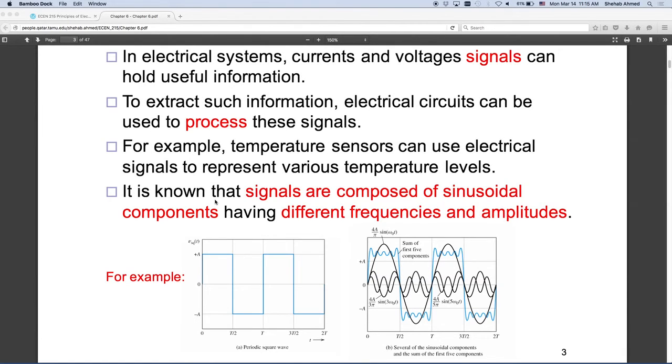In the electrical signal, you can combine signals of different frequencies put into the circuit, right? I can have two different voltage sources in series. Or I can just put a square wave, right? If I put a square wave into a circuit, a square wave is a periodic waveform, and since it's periodic, I can use Fourier series to chop it up into sinusoids, right? So it's like having many sinusoids at different frequencies being put into this circuit, right?